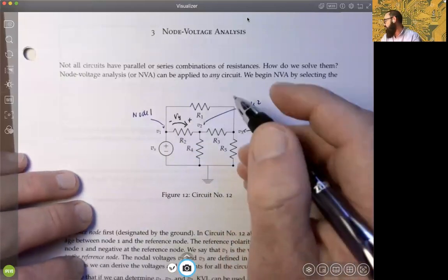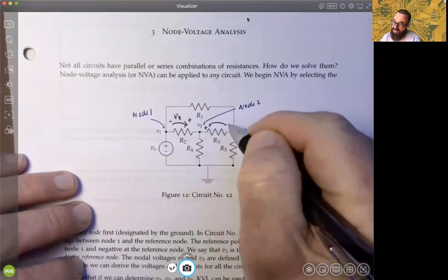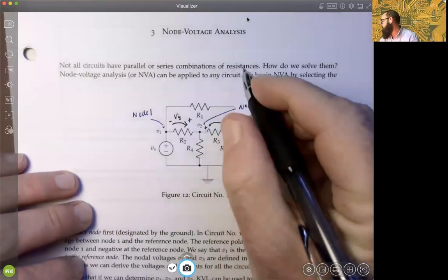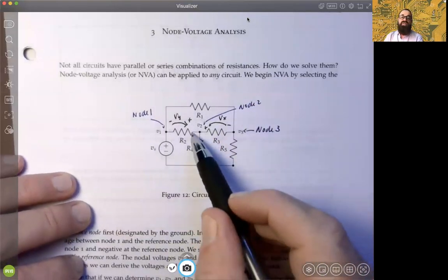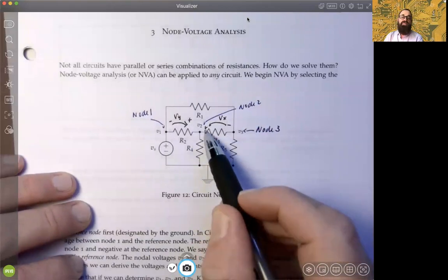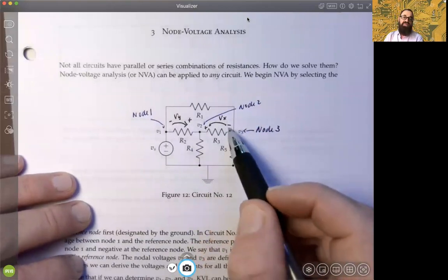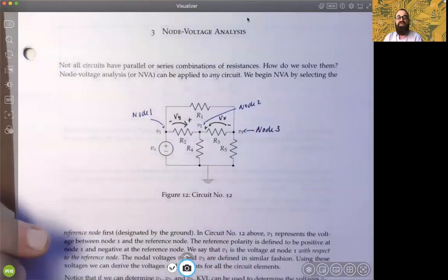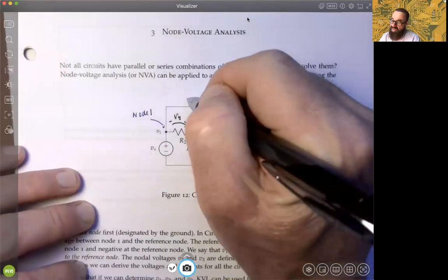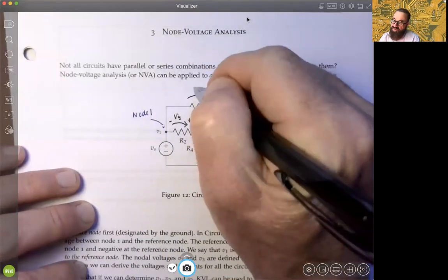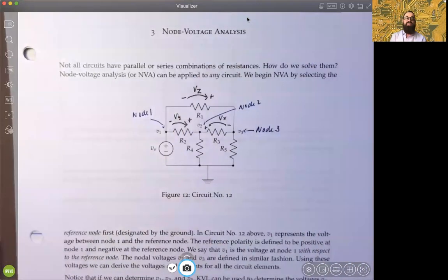Similarly, let's do that for R3. Let's represent a voltage arrow here. This is pointing to plus, minus, and let's call this V sub X, okay, that voltage X. Again, if you're traveling from left to right, it'll be a positive voltage. If it's from right back to left, you're coming into the negative pole, and that'd be negative, right? And then we can do the same thing up here. Let's just say arbitrarily, let's represent the voltage polarities for VZ, and this is plus and this is minus, okay?